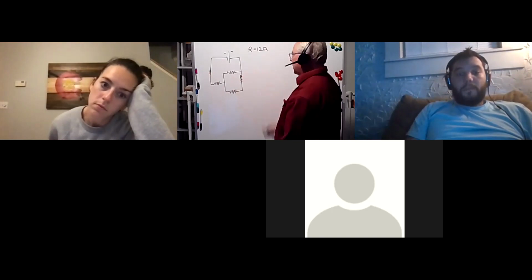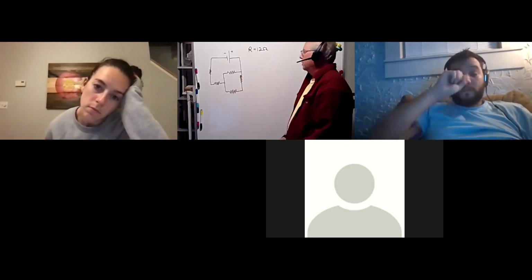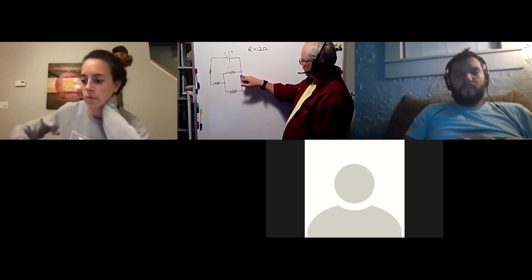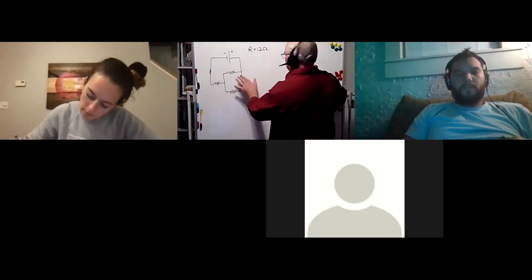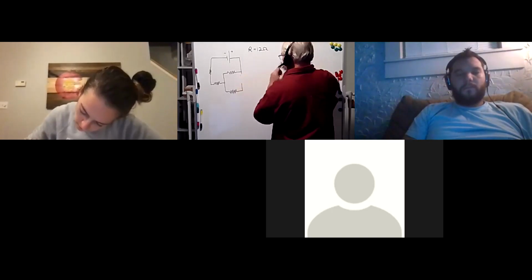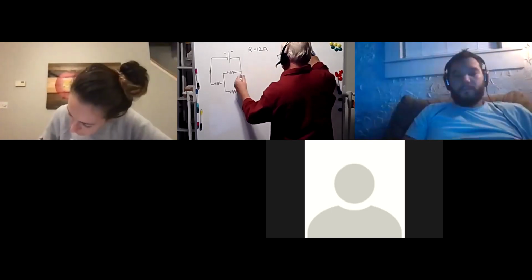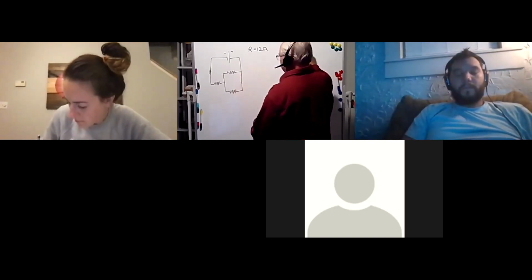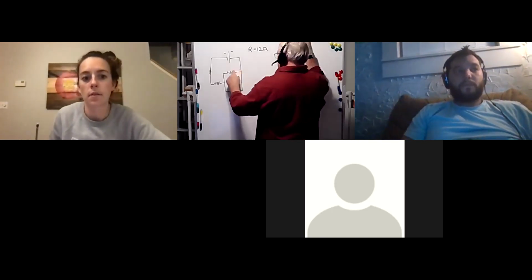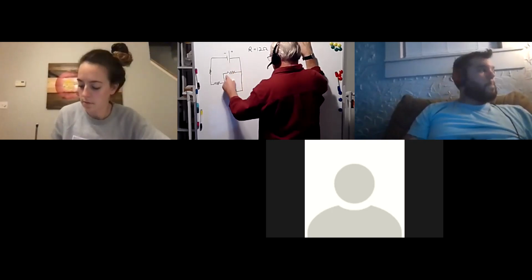I mean, they're stacked, but the answer is no, they're not in parallel. If this wasn't here, if this was just a straight line, I'm going to put this back in a second, but if we had that situation, yes, then these two are in parallel. Current splits up, and then the current comes back together.